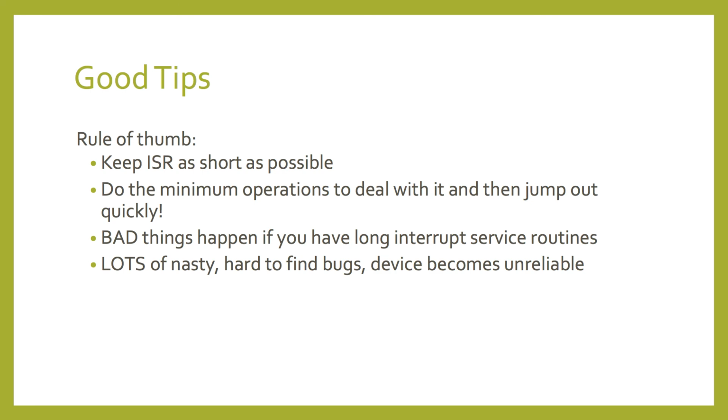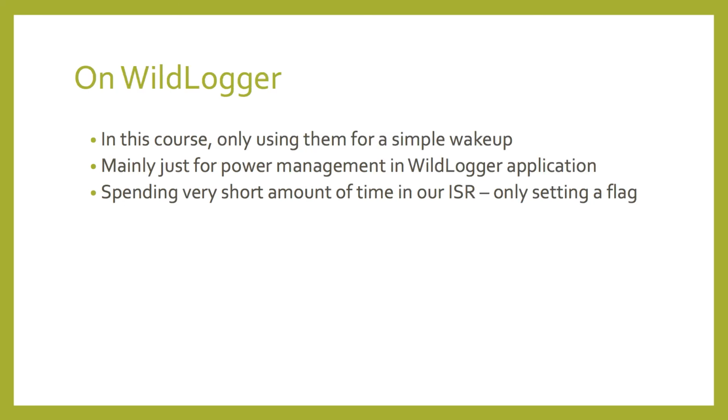The longer we stay in an ISR, the higher the chance that we'll introduce nasty bugs into our program that are notoriously difficult to find and then debug. So interrupts are actually quite a complex topic in embedded software development, and they're the principal engine behind operating systems and how they're designed. In our data logger, we're only going to use interrupts mainly just for power management, where we'll be waking up the device. So in our ISR routine, we're going to be setting a flag, then jumping straight out of it and letting another function handle the rest of the interrupt response.